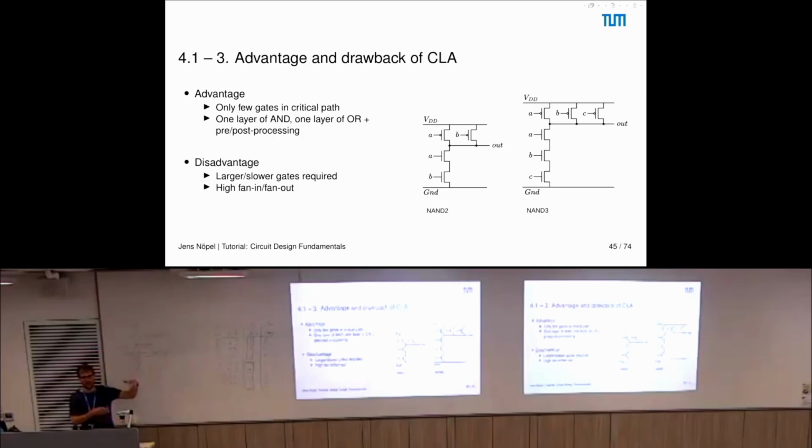So then you balanced your design. So what you usually do is, let's use a different color. If you talk about dimensions, in a normal inverter the NMOS dimension would be 1, and the PMOS dimension would be 2. I hope this makes sense so far.